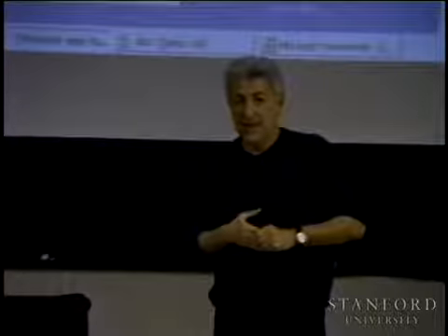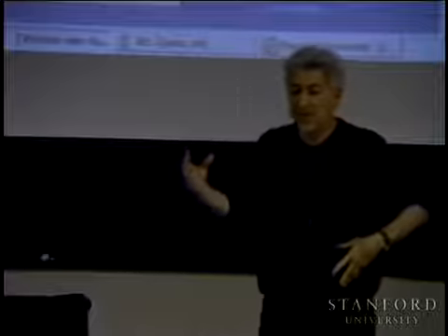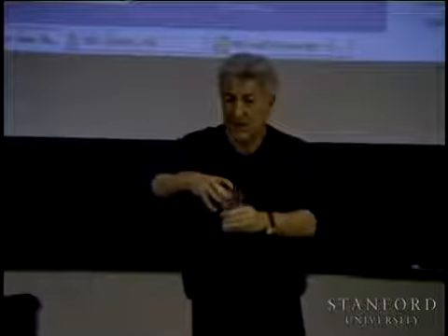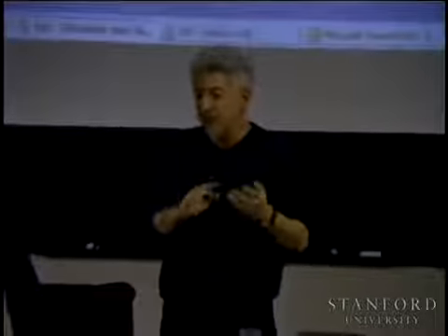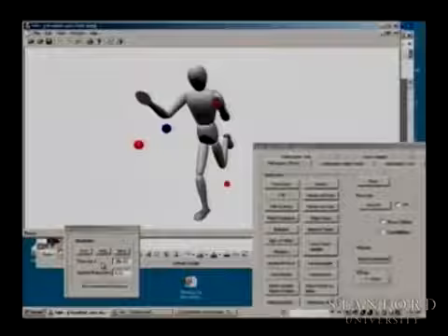It's not easy. It's already difficult for a 6 degrees of freedom robot like an arm, but for a robot with many degrees of freedom, suppose I would like to move to this location here. There are infinite ways I can move there, and many, many different solutions to this problem. In addition, a human does not really do it this way. When you're moving your hand, do you do inverse kinematics? Anyone? No. So we will see different ways of doing this. I will come back to this a little later.